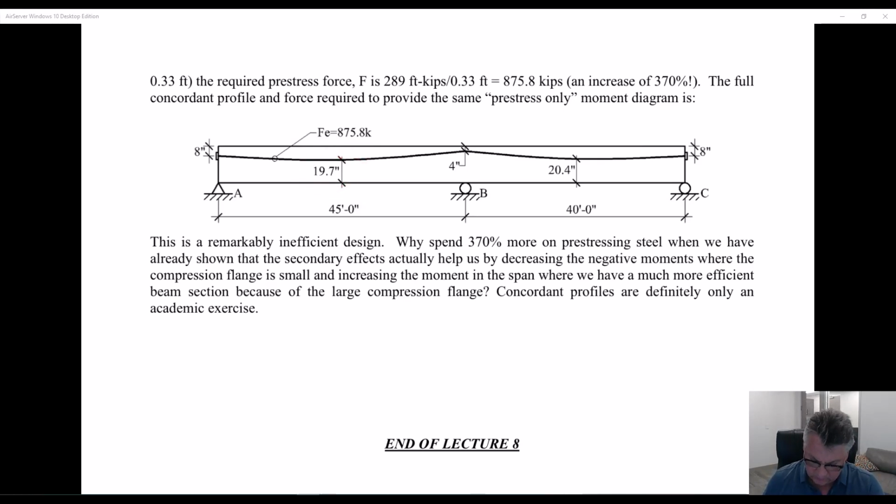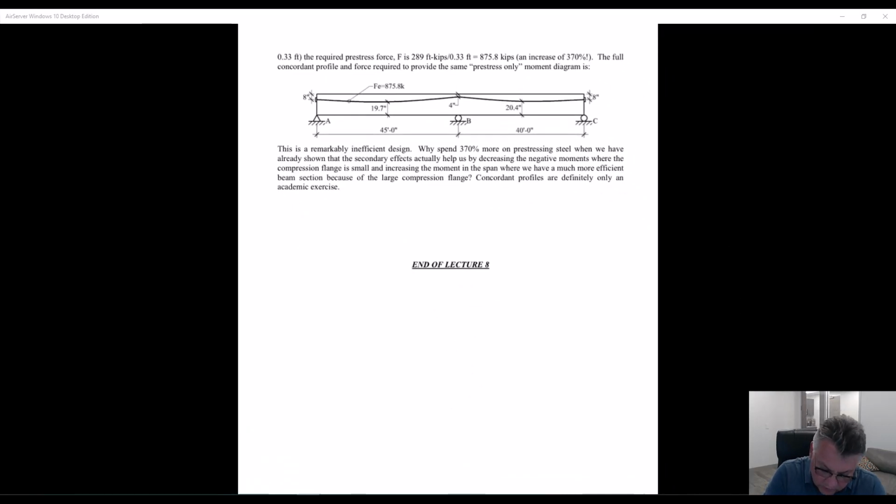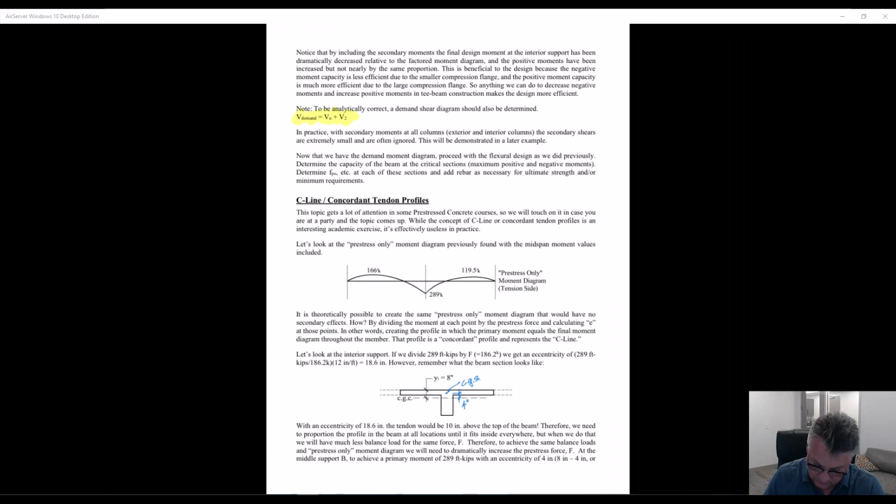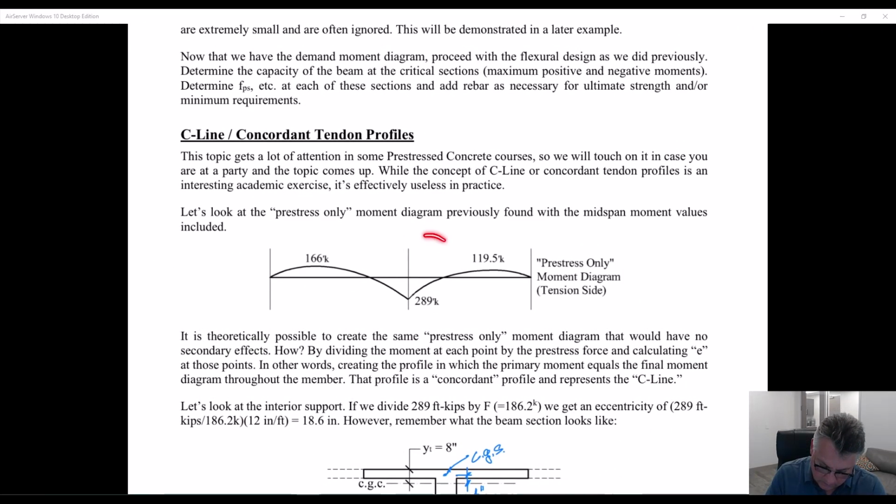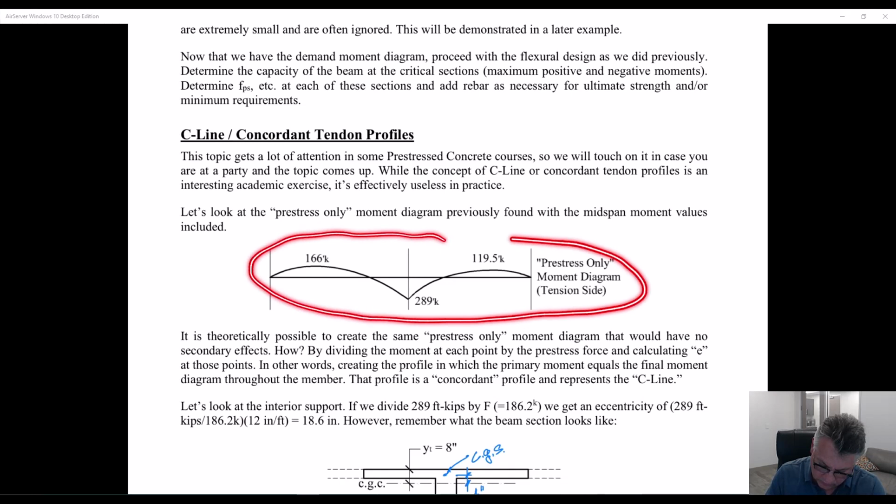So this profile would give us this force and this profile give us exactly the same final pre-stress moment diagram.